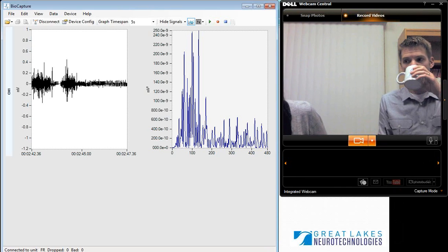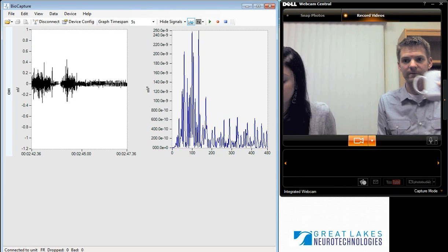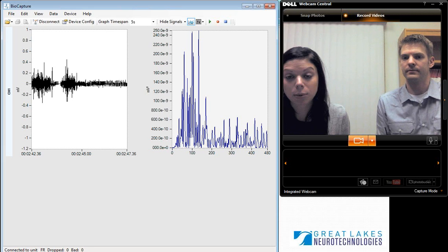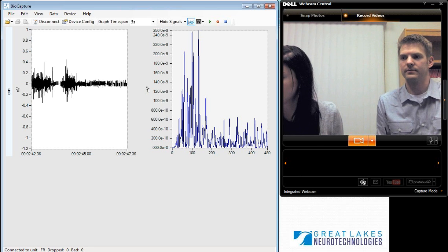Here's another question. You demonstrated EMG data acquisition, but the BioRadio samples at a maximum of 960 hertz. If EMG occurs typically between 0 and 500 hertz, is some of the signal being lost per Nyquist? And if so, how does the BioRadio accommodate for that? Certainly.